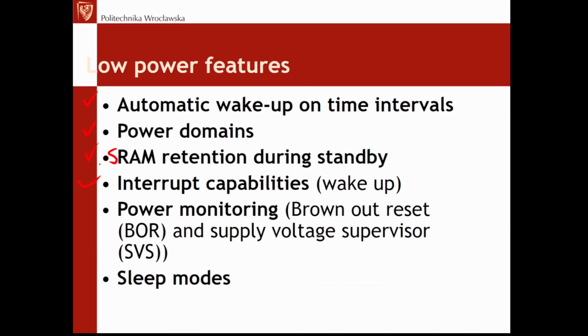But from the software developers' point of view, losing registers during sleeping usually means the necessity to reset and reinitialize everything, which means, of course, a huge waste of time. That's why RAM retention is sometimes much better, especially if we have periodic wake up of a microcontroller every tens or hundreds of milliseconds. It's much better to have the RAM retention feature than to miss it. So again, a feature that is well welcomed today in microcontrollers.